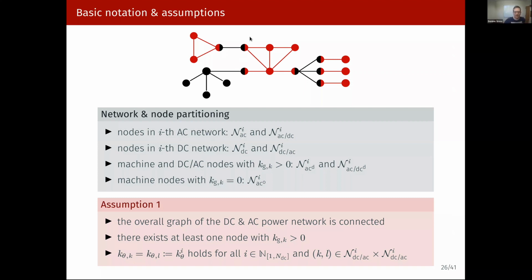You could imagine having a second HVDC from this node to this one here. And then if these gains are not the same on both ends of these two HVDCs, a certain frequency deviation in this network here would map into different frequency deviations at this node and at this node here. And then you're in trouble, right? Because then it can never synchronize. So that's encoded by this one here. So suffice to say, there are some gains where if converters are on the same DC network, they have to get the same gain, and that restricts what you can do a bit.